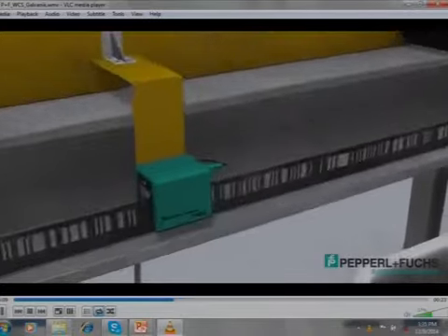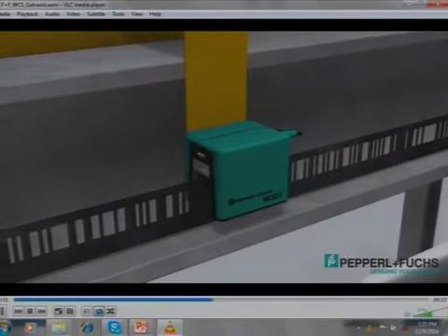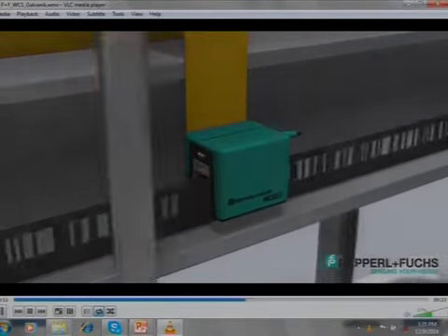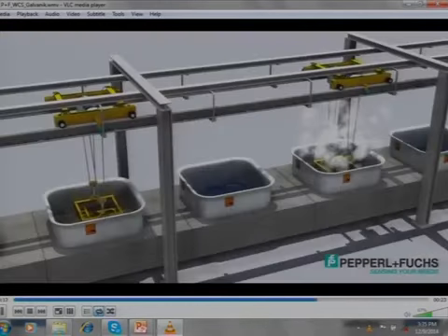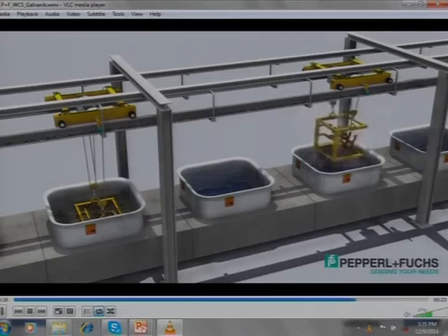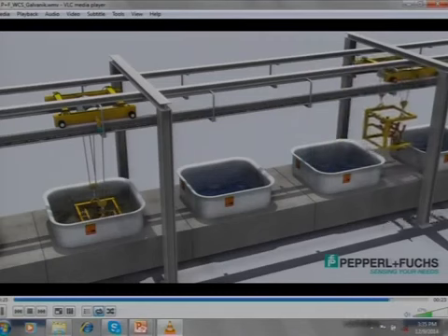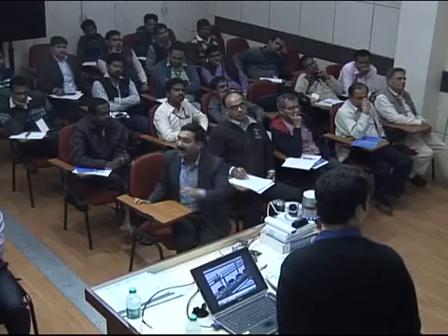One question. Why can't we have a normal encoder here? We can, as Sudhanshu said, we can have a cable pull system, linear to rotary conversion, and put a normal rotary encoder in a chemical plant.